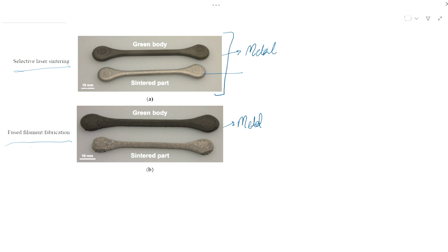But for complex geometries, if shrinkage occurs, suppose we want to print turbine blades, the complexity is much higher. So we cannot use such processes because the distortion of the curvature will be much higher. It won't be possible to control the deflection of the three different planes. We do not have any software to give the tolerance for this type of complex components.